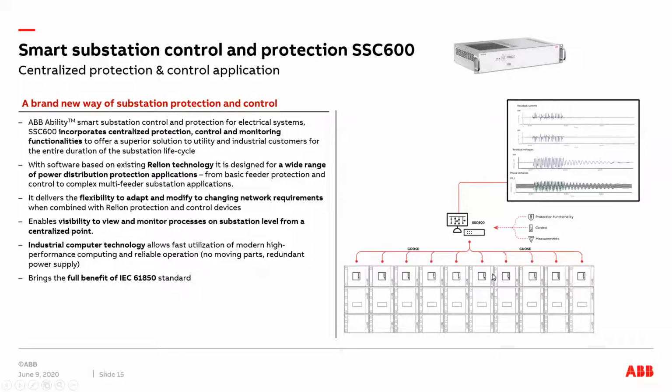It also works on IEC 61850, which we talked about earlier, which subscribes to the sample values from its respective feeders, and can also use GOOSE messages to do the interlocking and the signal sharing between the devices.